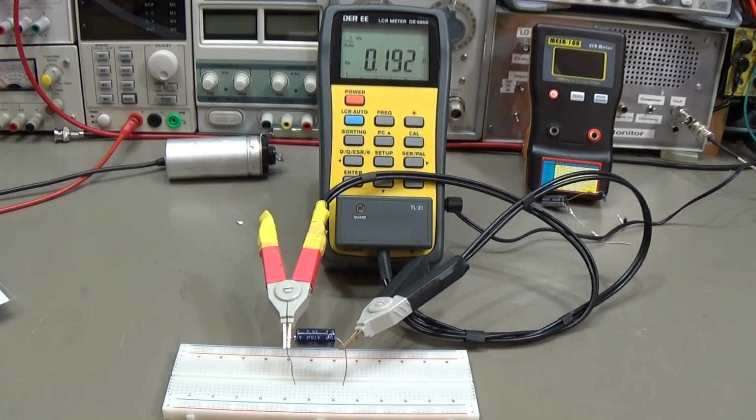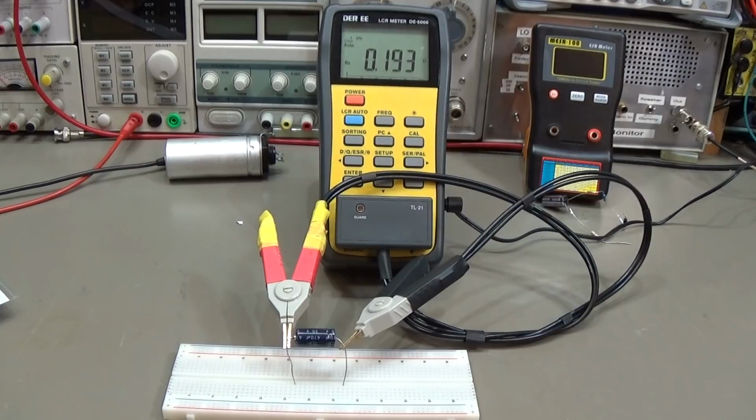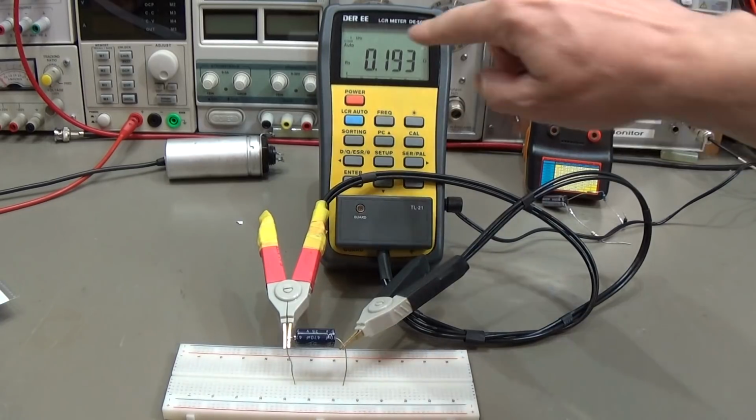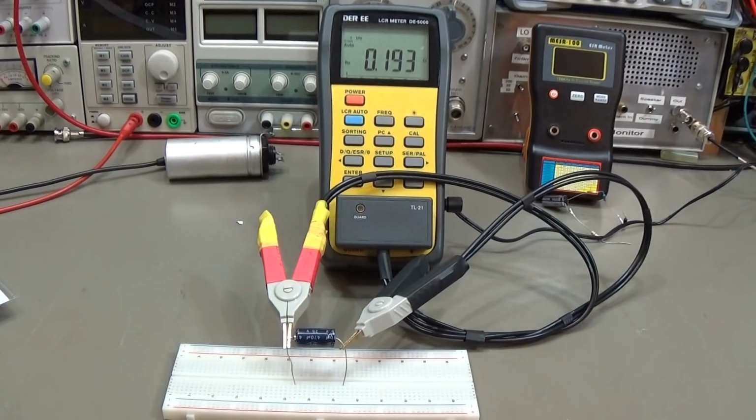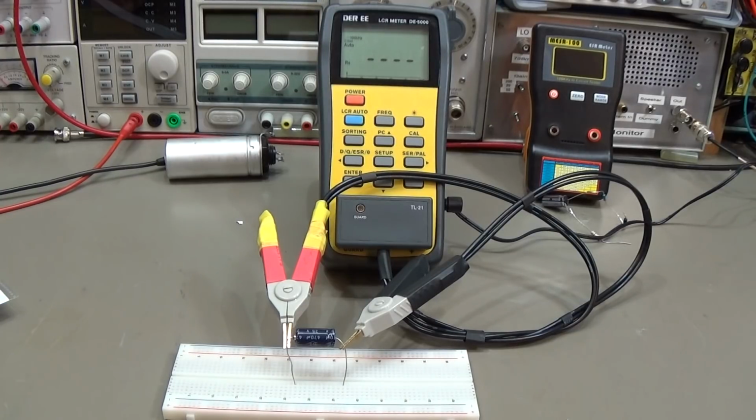And we just start off here with the question, why can we test an electrolytic capacitor in circuit? And you see I have here a 470 microfarad 25 volt capacitor, and we are already reading our ESR, but something is wrong. If you watch our test frequency, we know it is only 1 kilohertz, and that's too low. So let's change our frequency to 100 kilohertz.